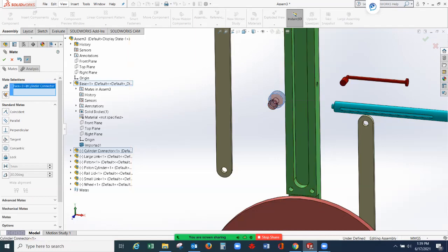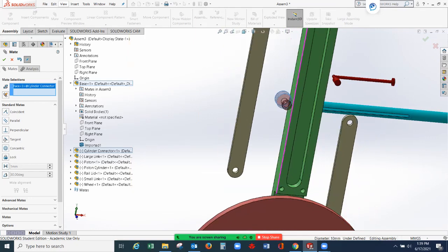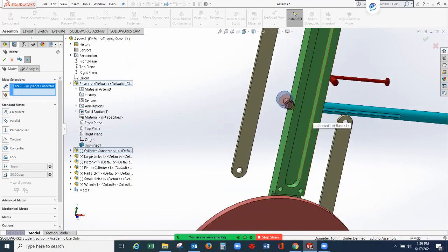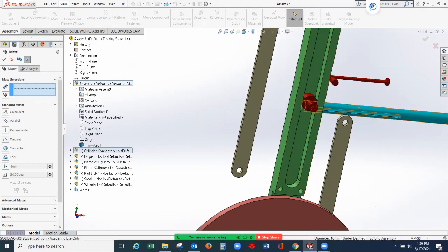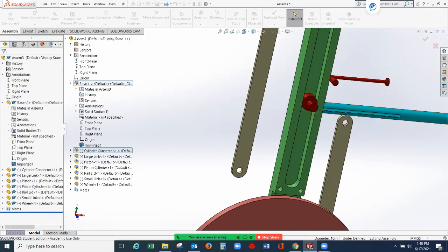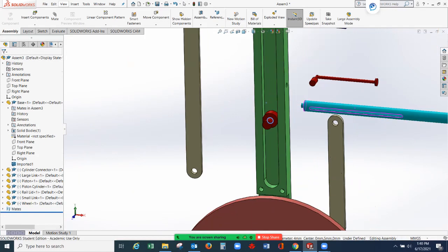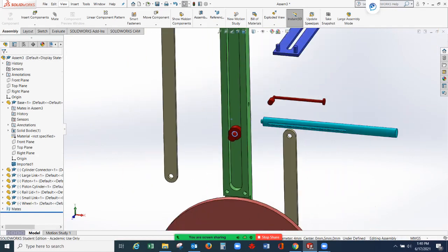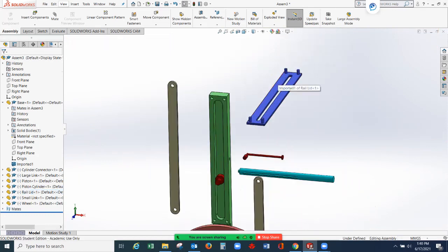So this face of the connector onto the face of this base. Select this green check mark. Just to check for a while, this is sliding inside the base. Now we need to cover it with this rail lid. Okay, so we call it a rail lid.